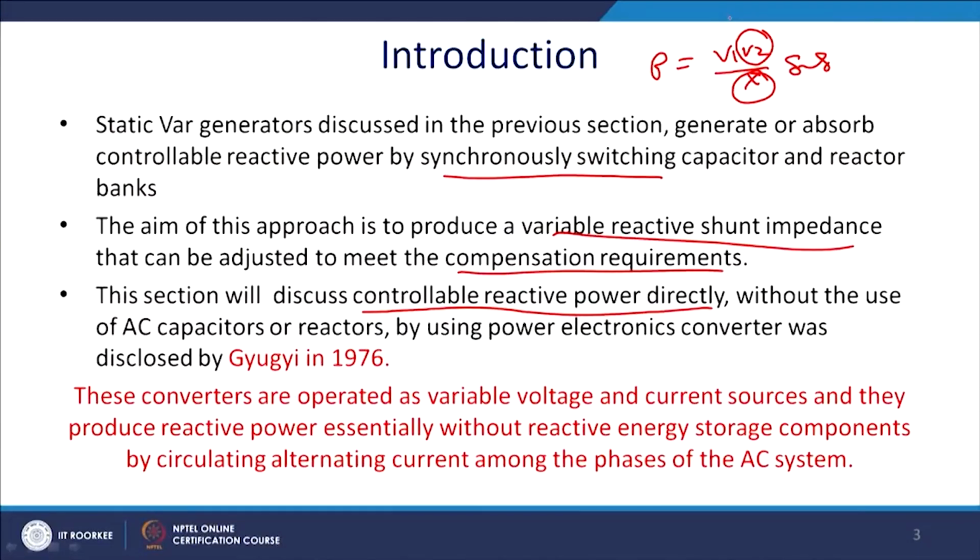without using an extra capacitor or reactor, by using a power electronics converter as discussed by Gyugyi, the famous writer of the famous book on FACTS devices with Hingorani. This converter is operated as a voltage source, current controlled inverter or converter.